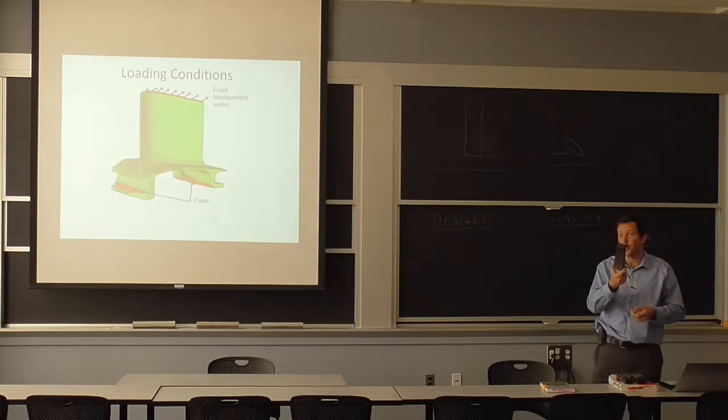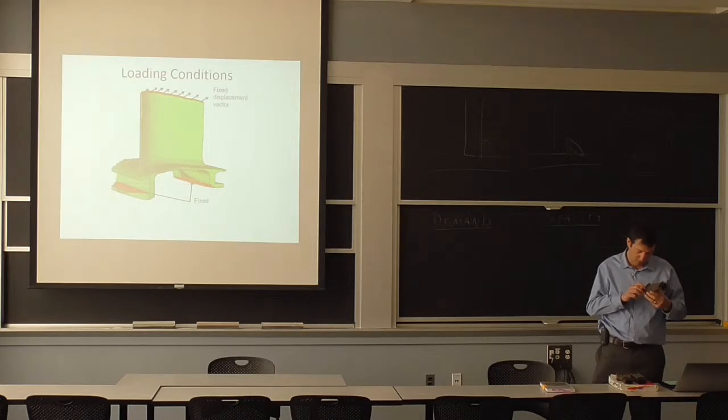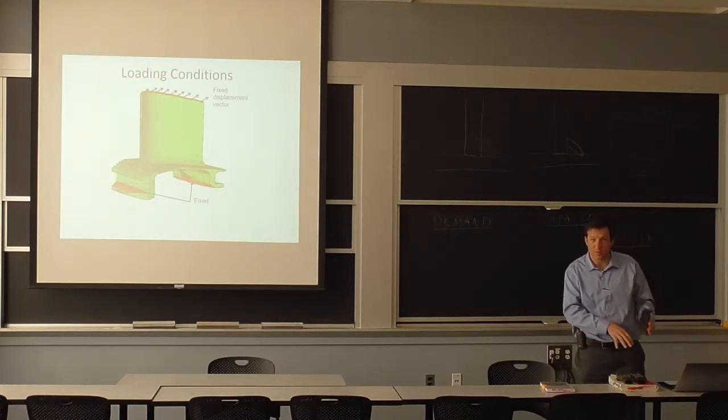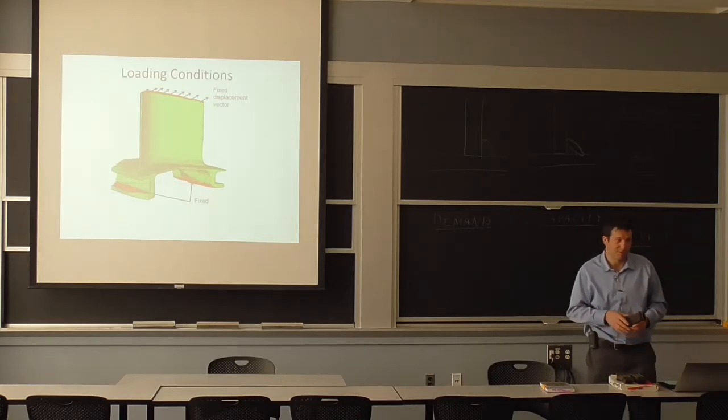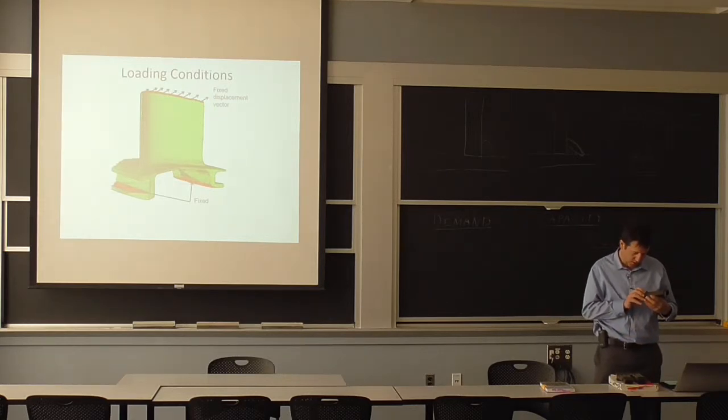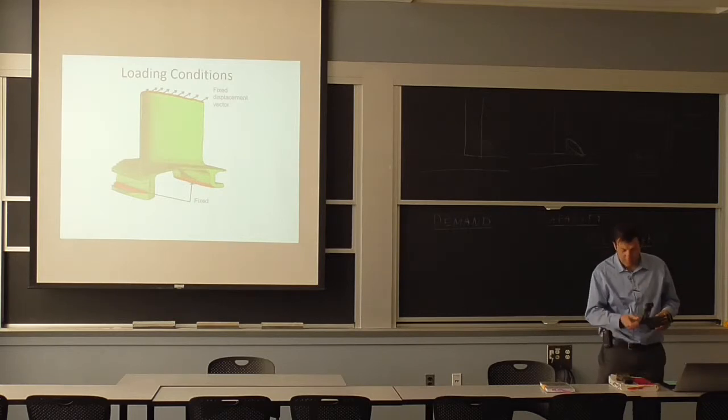This one doesn't have holes. What it has is damage at the very bottom here. And there's one of them that is starting a crack. So I can't say for sure. I was actually not doing this one. But I would start to think that if there's very hot, high pressure air that can start to penetrate from one end, then maybe bad things can happen.